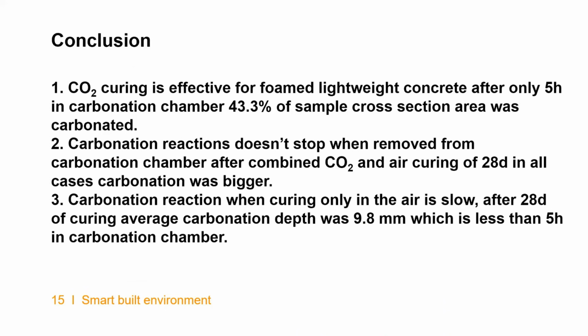So, conclusions of this study. We can see that CO2 curing is effective for foam concrete. After only 5 hours in the carbonation chamber, 43% of the sample cross-section area was carbonated. The carbonation reaction does not stop when samples are removed from the carbonation chamber after combined carbon dioxide and air curing of 28 days. In all cases, carbonation was bigger, and the carbonation reaction when curing only in the air is slow. After 28 days of curing, the average carbonation depth was only 10 millimeters, which is less than what we got when cured 5 hours in carbon dioxide.